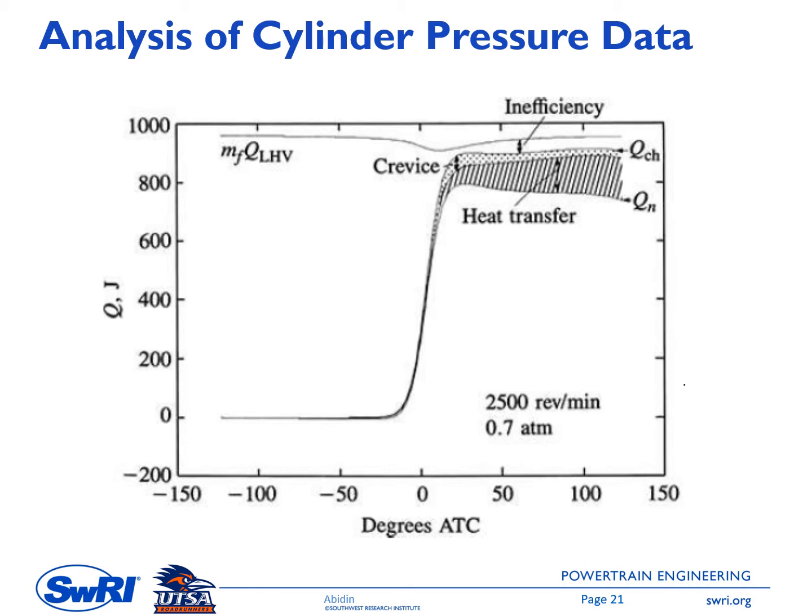The top line here is the fuel energy, and then you will have some inefficiency. This one is the combustion efficiency. Let me put a yellow here. This yellow one represents the fraction of the unburned fuel or unburned hydrocarbon. So this is the fuel that will flow out of the engine along with the exhaust gas.